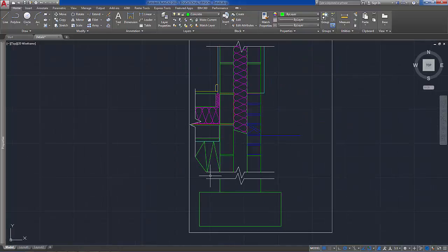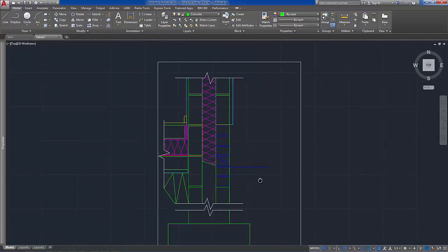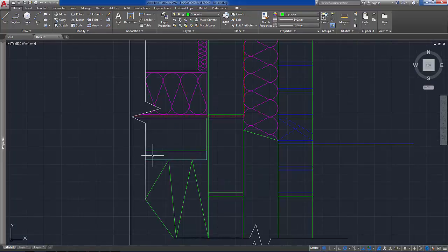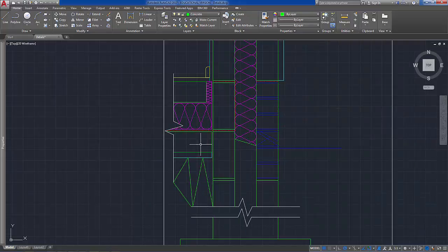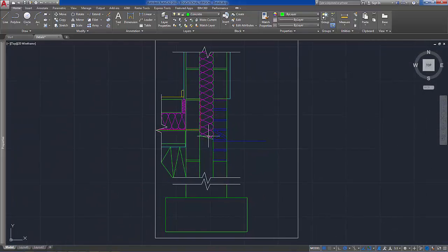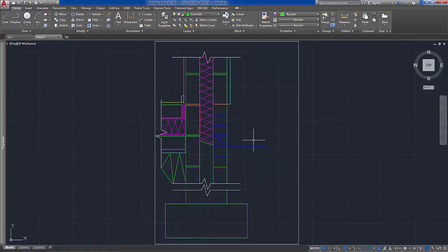Basically, there does need to be backfill once the excavation has all been completed and everything built. Then you do need to fill in the rest of the void with backfill material, or hardcore, or blinding, as it can be called. Basically, it's quite coarse stones, and this level here indicates fine blinding or sand can go in there before the concrete will be poured. The next thing to do then is some hatching. So a few examples of that.